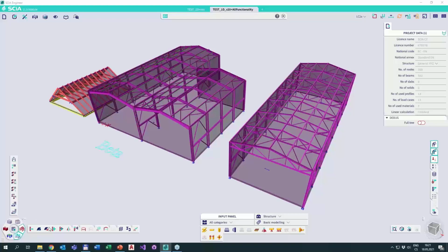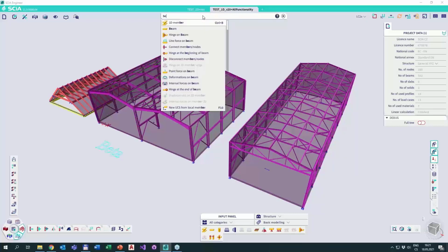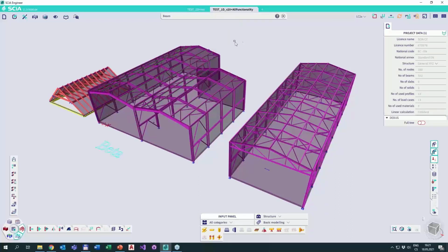You can not only place the commands like one next to each other, but there is also possibility of stacking them. Yeah, there are some similar commands. Here, for example, I have mirror and rotate. I also think that the join and divide surface are sort of similar commands. So I can just move one on top of the other, and then I have both of them here. Of course, I can reorder them so they are maybe last in my editing functions. So all these options are possible, and the same or very similar to the menu. If I, for example, want hotkey B for beam, I just click here, write B, and B is my new hotkey.